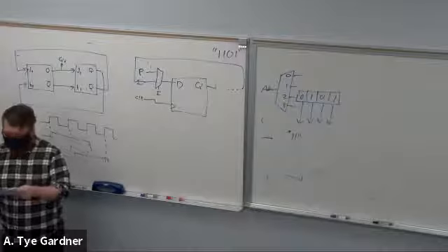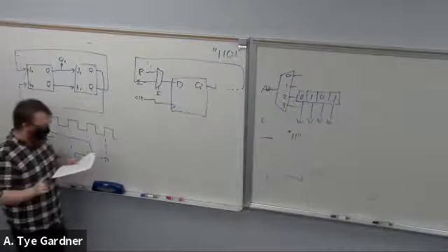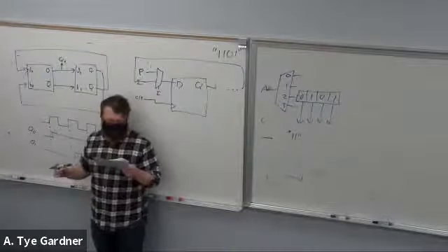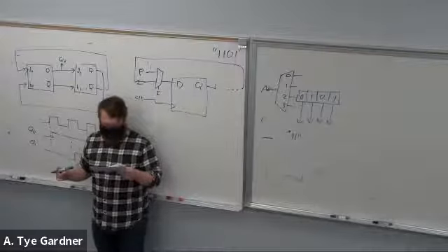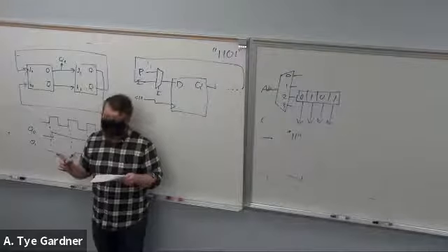All right, number 18. I believe I put 7 errors in here and asked for 5. The first error is on line number 4. Missing parentheses. Line number 5, it says end component. It should say end outer sub. Line number 17 is missing a semicolon. Line number 30, there's a lot going on here. I misspelled bitwise. Then inside the port map, I'm missing a comma after the sum, and sum is not declared.